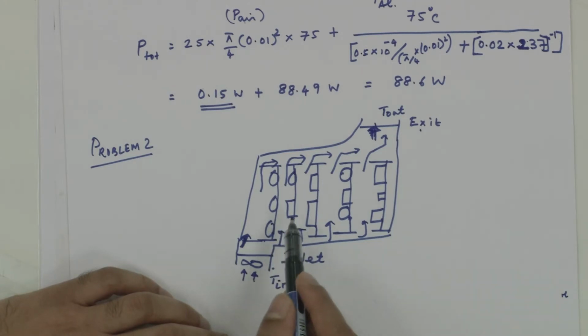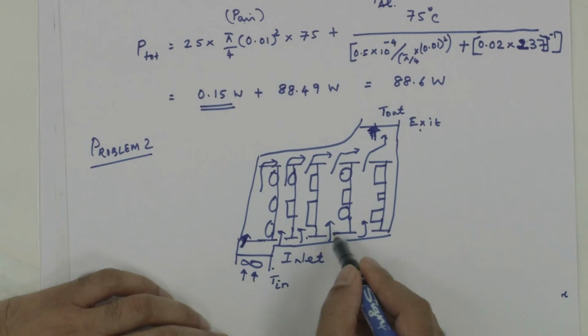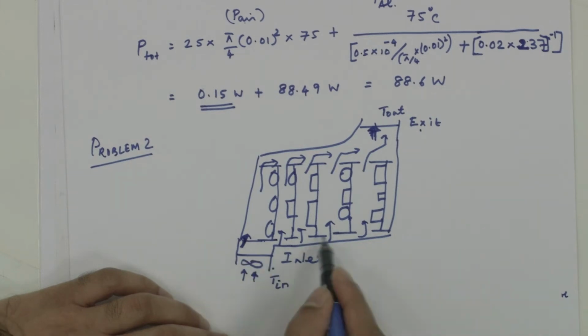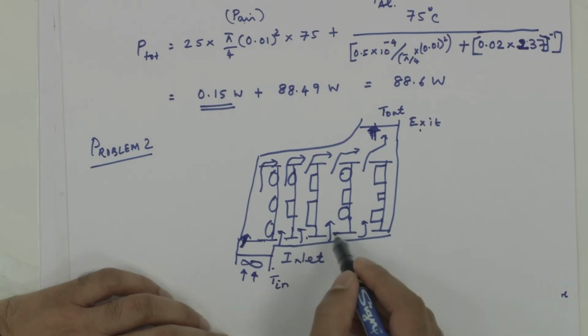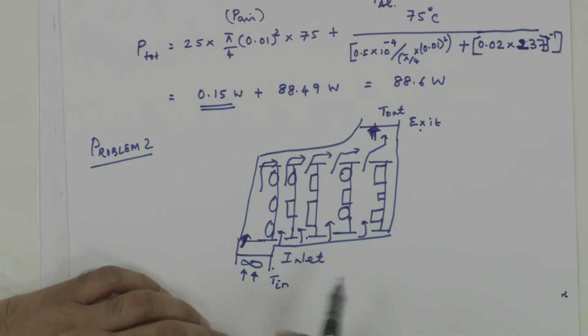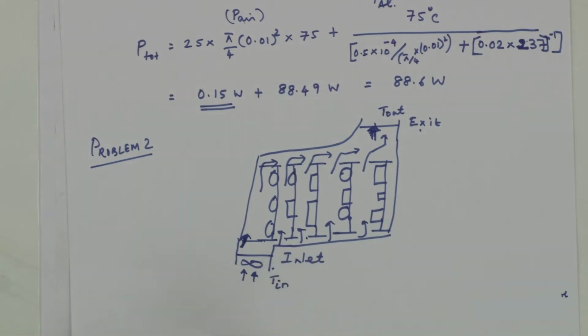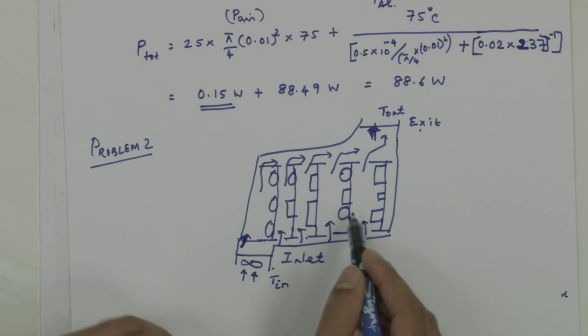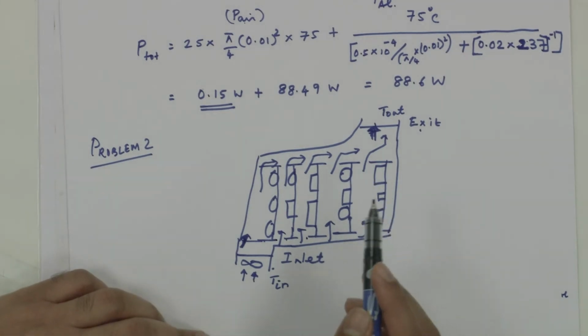Depending on that, one may have to modulate the flow, and that is often done by putting an orifice at these inlets. These orifices are pressure drop elements. If the fan is operating at a fixed speed, then these orifices provide a way to modulate the flow so that the appropriate amount of flow goes through each and every one of those boards.